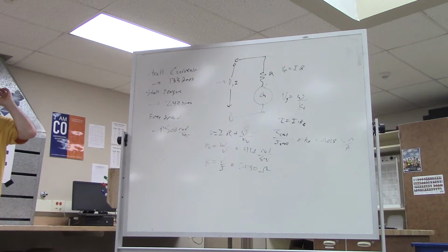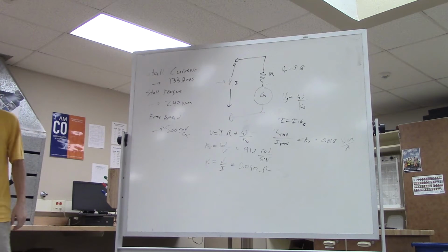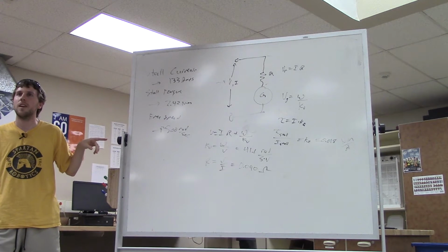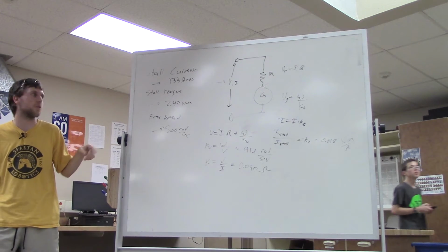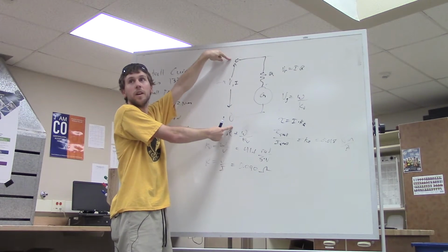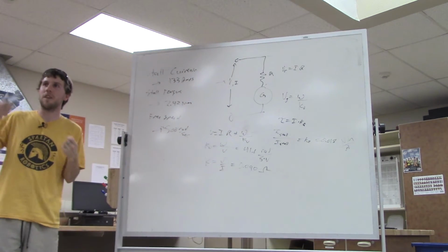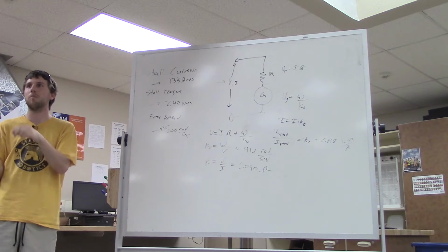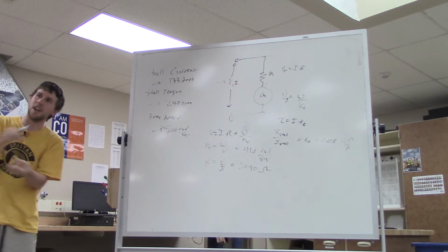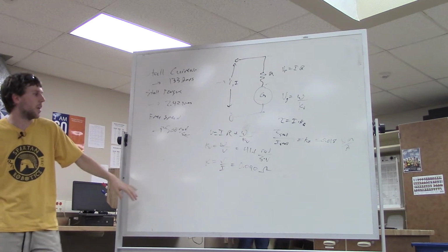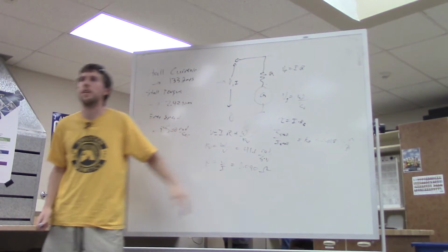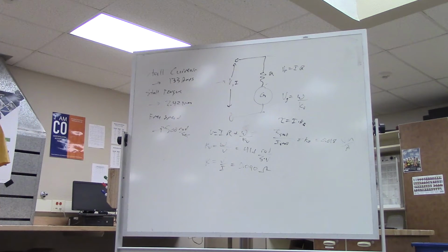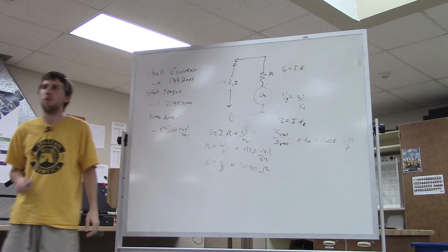Sorry, what was your statement? Well, I'm just saying, I don't think we'd be putting 133 amps through this thing in the context of FIRST Robotics. You get pretty close, but what ends up happening is there are other voltage drops. This is from the lead of the motor to the lead of the motor, not from the battery to the battery, right? So you'll have resistance in your wires, your fuse, the PD board, and the speed controller, and then you have to undo that again. Maybe 50% of that resistance will come from the rest of your system. So that's a reason to keep your wire run short. Use big gauge wire from your battery to your circuit breaker and keep that short, because that lets you minimize the rest of the resistance so that you get more voltage to your motor.